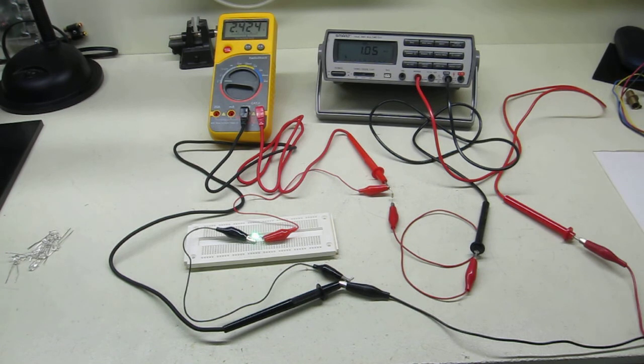Next, increase the voltage so that the current in turn increases in approximately 1 milliamp increments. Now, it's not necessary that they be exactly 1 milliamp, 2 milliamps, 3 milliamps. Since we're going to graph this on Excel, as long as we get close, we're fine. We need 10 points approximately 1 milliamp apart. So in this case, 2.09 milliamps, 2.654 volts. And we simply increase the current accordingly, writing them down each time, plugging them into Excel.